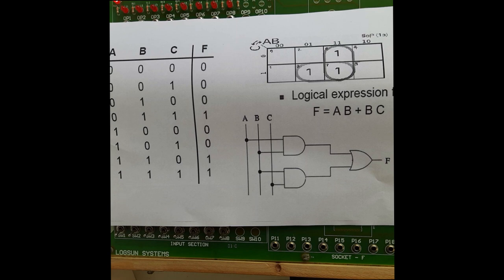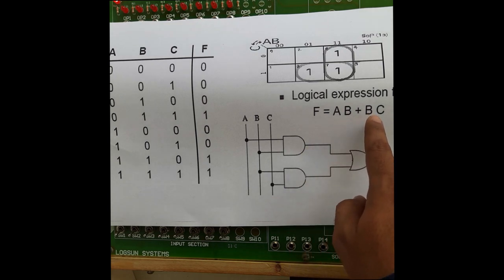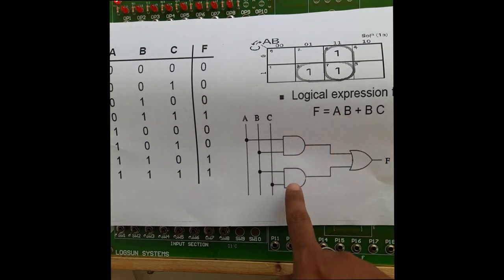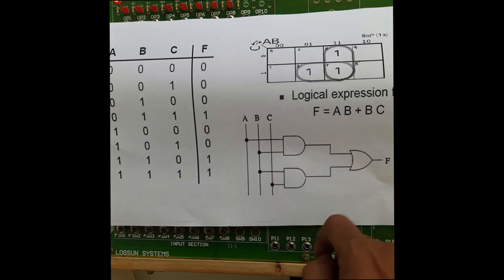Now here we'll start our implementation part. Keep in mind our equation is A into B plus B into C. So the first AND gate is A into B, the second AND gate is B into C, and both we are connecting with an OR gate. Before implementing the circuit diagram on a digital trainer kit, you need to assign numbers to the logic gates in the circuit diagram, so it is easy for you to implement. Now for this example I am considering